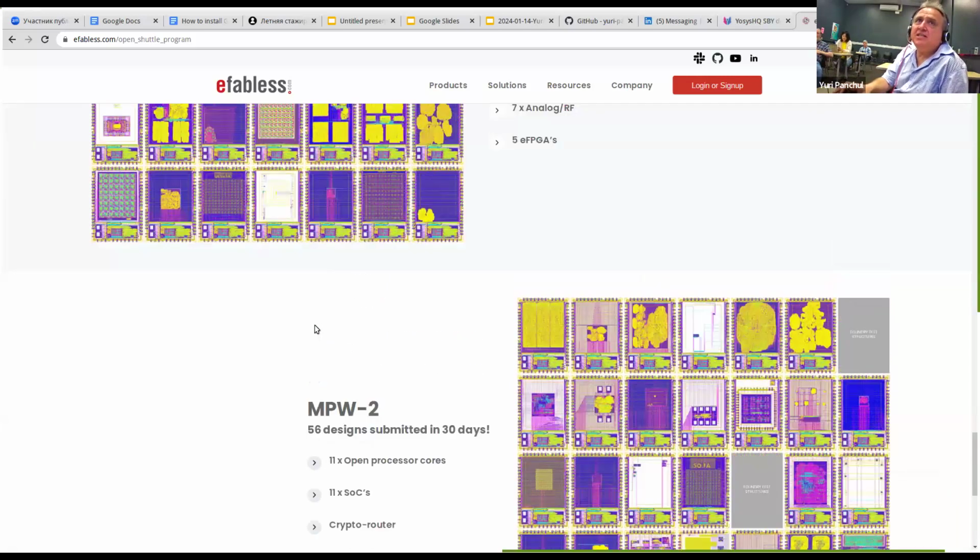Now you would say, oh, come on, this is obsolete technology, but this is not true. First of all, a microcontroller which controls the engine in a car usually does not use technologies like 3 nanometer, because it will not survive near a hot car. Plus it's a much smaller initial cost for manufacturing.